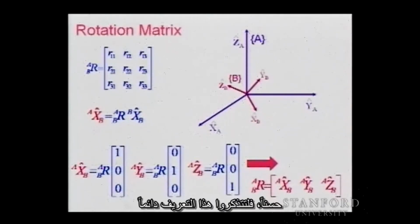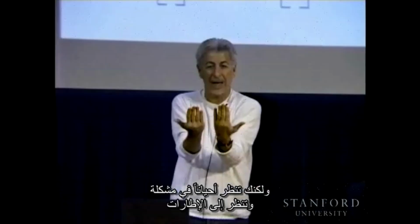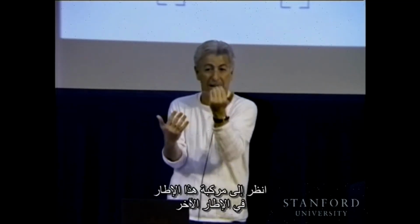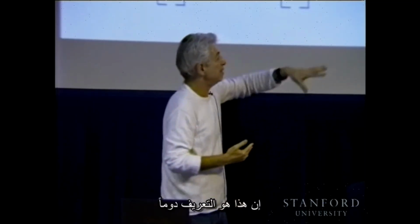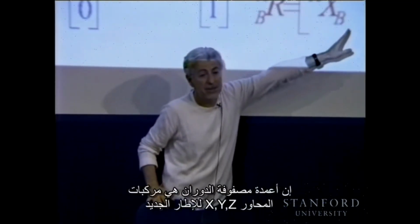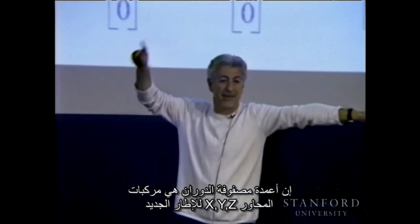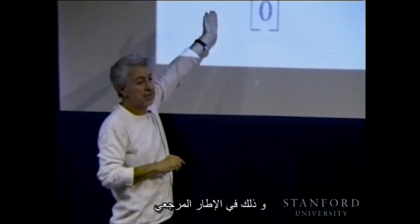Always remember this definition. This is very, very important because we are going to find the rotation matrix in many different ways. But sometimes you are looking at a problem and at the frames. Look at the components of that frame in the other frame, and you will make sense of your result. This is always the definition: the columns of the rotation matrix are the components of the axes x, y, z of the new frame in the reference frame. Okay?